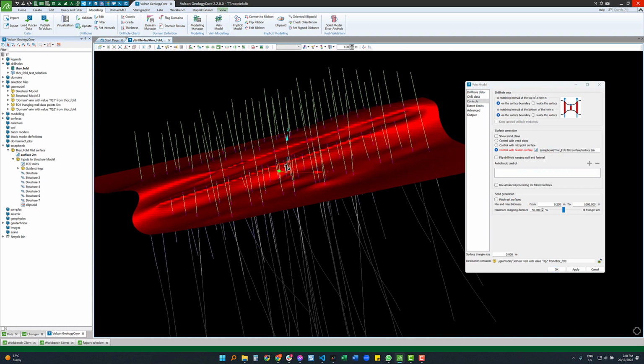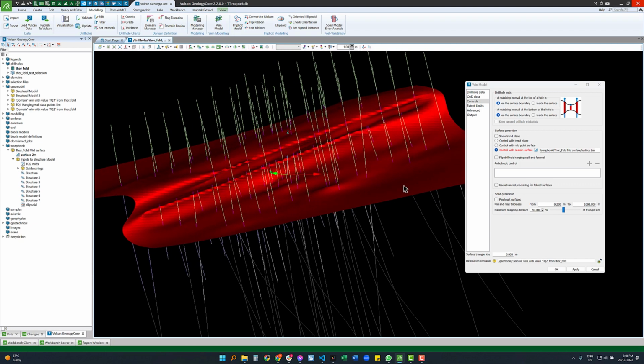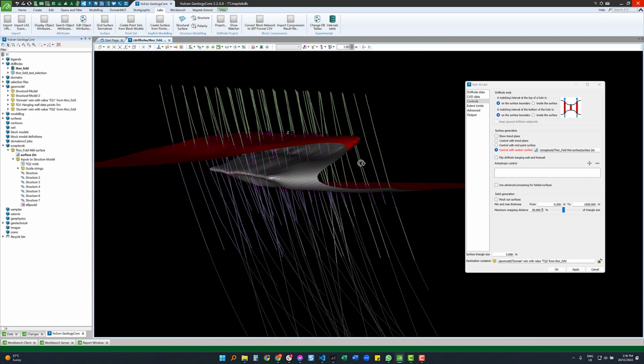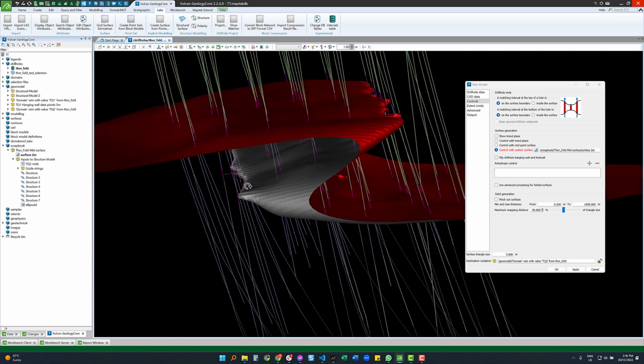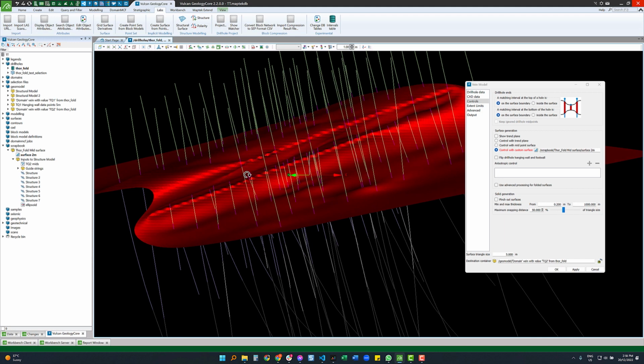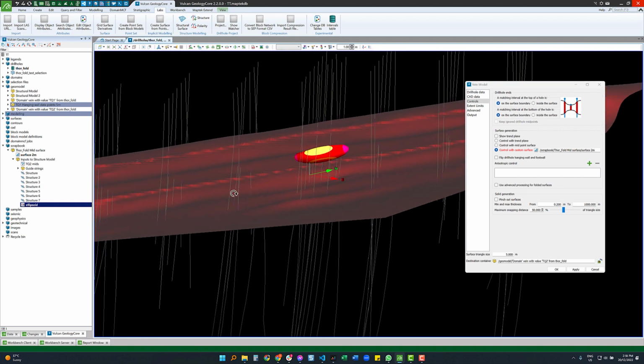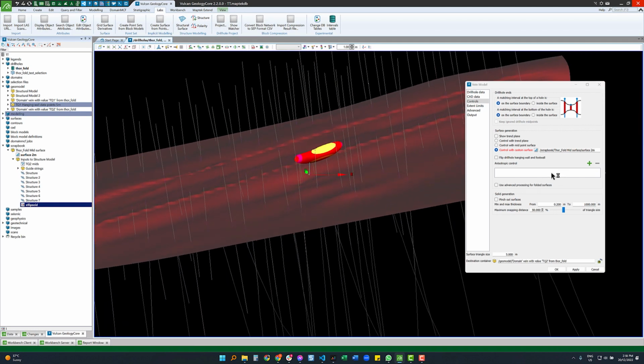And basically the way I did this is I dumped out the midpoints from the vein modeler, and then I used the structural surface tool and a couple of structures, well, 7 structures I suppose, so a few structures to just kind of get it to do what I wanted. There's a few sort of guide strings as well, because it doesn't align super well really. So a few things to kind of control it, but once you've got that mid surface that's representative of the actual midpoints that you've got, that's a good starting point that we can use. I also used an ellipsoid to generate that, to get it to kind of align the way that I wanted. So I'm going to use that in my vein model as well.